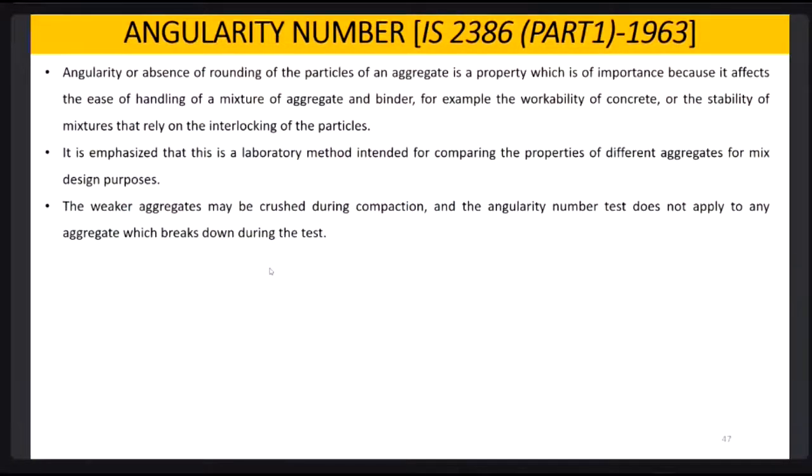One more thing. If your aggregates get crushed during compaction, then the angularity number test cannot be applied on it because the material is already crushed. So we cannot do the angularity number test on it.